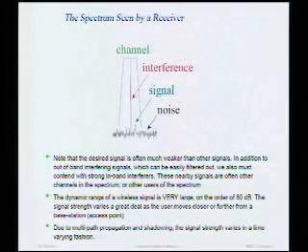And so I'm not receiving just one signal, I'm receiving an ensemble of signals. Depending on the phase of these different paths, these signals may add in phase or they may subtract. Let's say I'm communicating at 10 gigahertz, where the wavelength is on the order of a centimeter. If I just move a centimeter back and forth, I'm changing the phase of these different paths by an order of a wavelength, so I can get a significant change in the amount of signal I'm receiving. This is called multipath propagation.